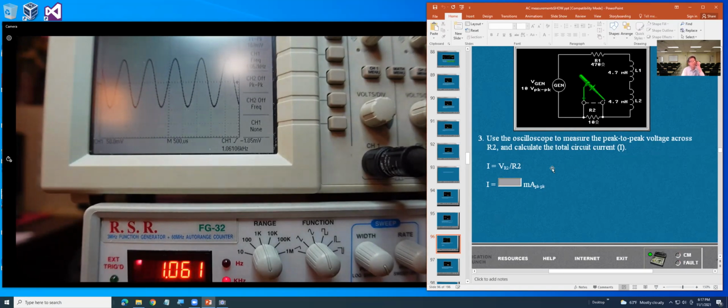And you need to press auto set measure. And it will tell you on channel 1, we have peak to peak 182 millivolt. And the signal is really very clear, no noise.